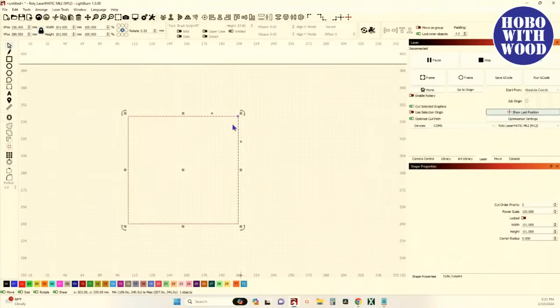Exactly. So now you've got this mysterious blue dot that's generated when you create from the rectangle tool. Will that change in 1.6 to where it's a control feature as well? It's control, yeah, in 1.6. Okay. But right now you don't have to hit control. You just have to highlight it, and once you do, it'll turn to the radius tool. And if you click it and then scroll to the counterclockwise position, you will get a live radius tool. And then as you come counterclockwise past the point, you get the negative radius.